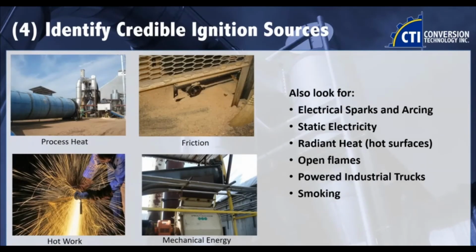With that, you want to identify your ignition sources, whether it be electrical sparks, static electricity, which is kind of that hidden gem, hot work, process heat, friction. Friction is something I'm dealing with now at another facility where they had a bearing overheat due to a bird that was making a nest on top of the bearing and dropped material onto the rotating shaft, which caused friction, which overheated the shaft and got into the bucket elevator. It was a whole big thing.